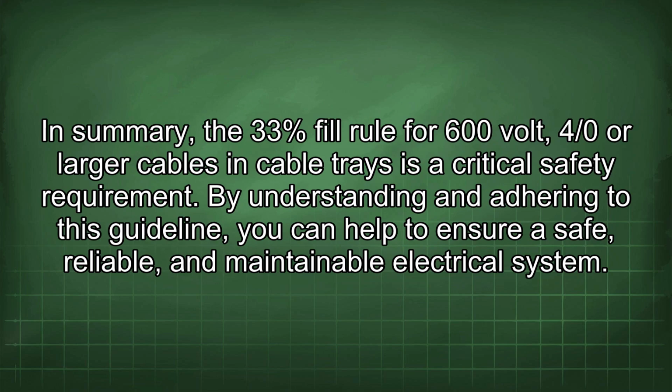In summary, the 33% fill rule for 600-volt 4/0 or larger cables in cable trays is a critical safety requirement. By understanding and adhering to this guideline, you can help to ensure a safe, reliable, and maintainable electrical system.